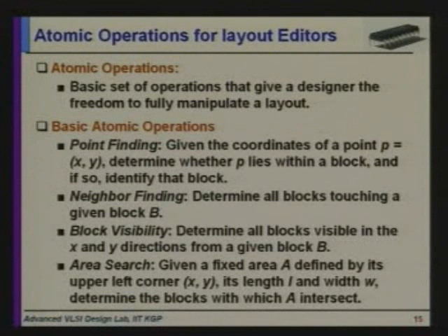Area search. So given an area, given by its left corner, x and y coordinates, its width and its length, we determine the blocks which intersect with this area A, right? So what may be the reasons? Maybe I have an area and I want to place a block in that area. So I first need to find out what are the blocks that are intersecting, right? Then I need to somehow move those blocks, make that free space and put a block in that area. So this is why it's required.